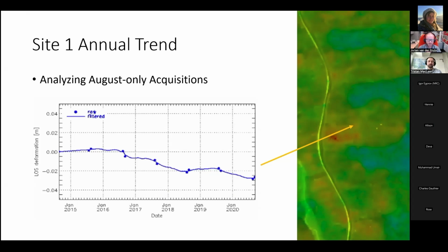Yeah, so the difficulty with phase unwrapping in this area that I'm looking at is that there isn't a stable bedrock reference, but there is bedrock south of Inuvik. So I can do that phase unwrapping with the Sentinel-1 data where that bedrock is located. Since you know where your stable point is, you can infer that throughout the rest of the interferogram.